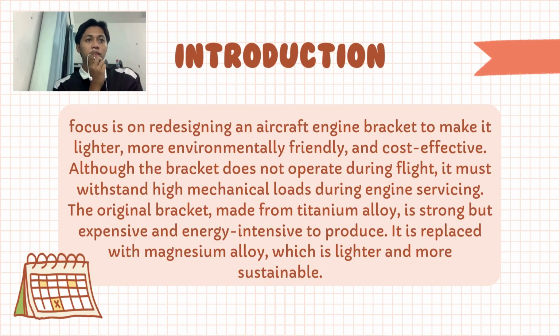Our main focus is on redesigning an aircraft engine bracket to make it lighter, more environmentally friendly, and cost effective. Although the bracket does not operate during flight, it must withstand high mechanical loads during engine servicing. The original bracket, made from titanium alloy, is strong but expensive and energy intensive to produce. It is replaced with magnesium alloy, which is lighter and more sustainable.